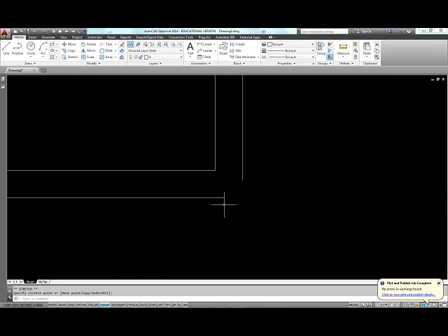Now we need to clean up this corner, so let's choose this line, choose that handle, and we'll say at 250 comma 0 to extend it to the same location as the line, and then choose this handle, put it on that handle, and you're done.